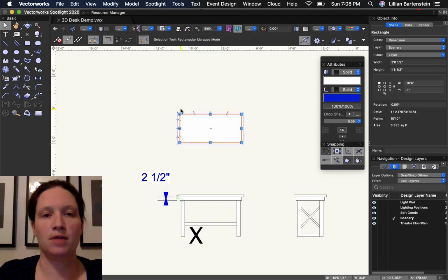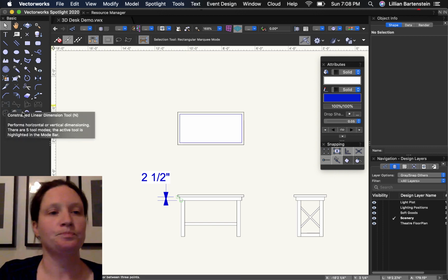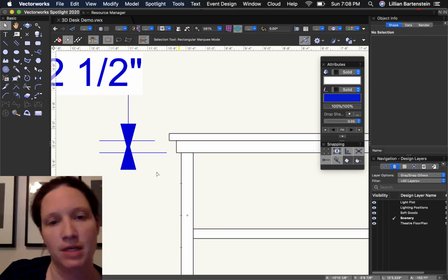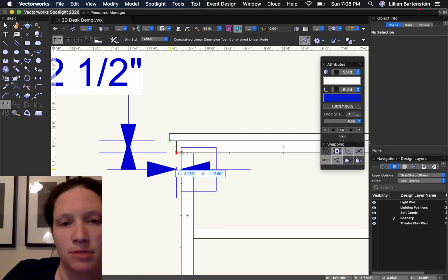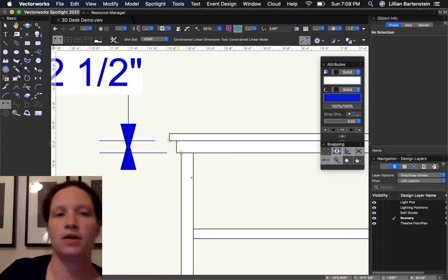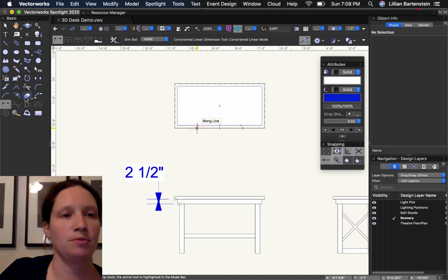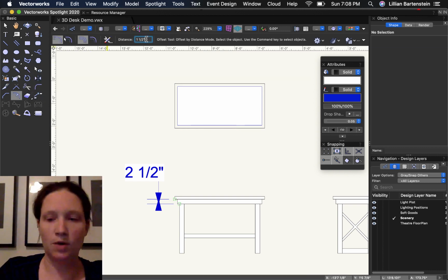Great. So now I can delete my initial extra rectangle that I just drew. Click delete, delete. I'm now going to use my offset tool again. Let's see what dimension that should be based on my other drafting. So how much space is this? That's 1 inch. Great. So now I will change my offset with my offset tool to 1 inch.